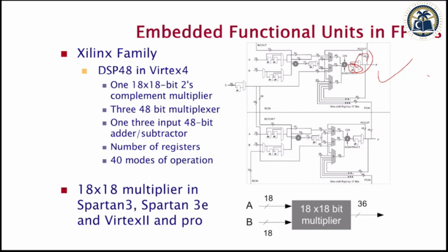So it depends. If you see, there is a parallel path, a path going through 2 registers, and a path going through 1 register. So there are 3 paths. But this is a resource, and all these registers are resources. So it will check whether, before you multiply, you are using a direct path, one register, or two registers. It will accordingly map your RTL Verilog code to this design.